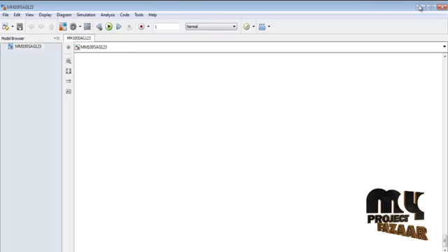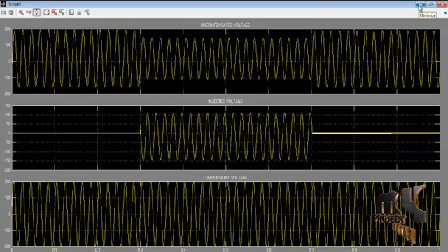In this process we designed two kinds of cases: one is sag oriented compensation, and the other is swell oriented compensation. First we see the sag oriented process. Sag means the voltage is reduced, due to a nonlinear load, for some seconds only. In those seconds the voltage is injected to increase the level to the normal source level.